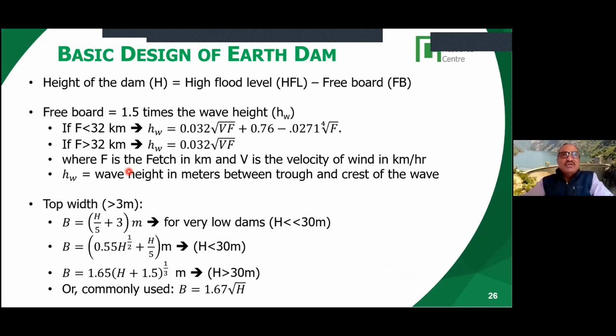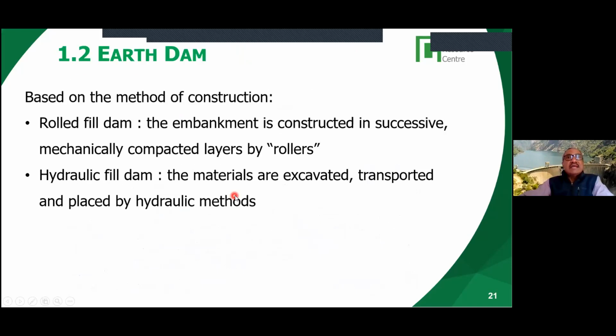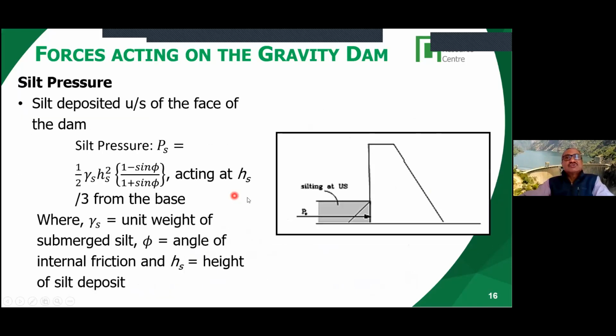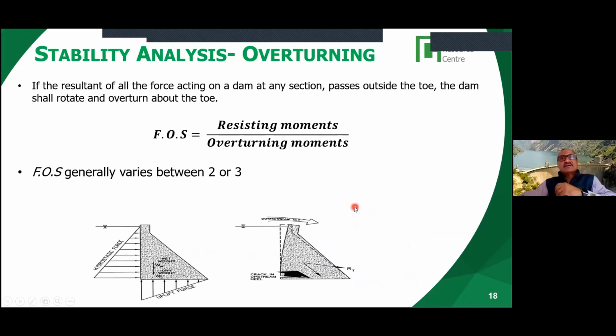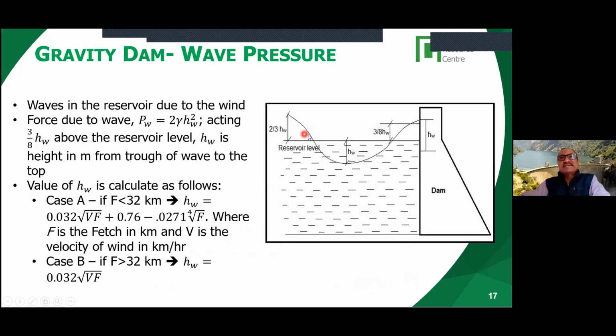So we use two methods. One is when the fetch is less than 32 kilometers; this gives the height of the wave that is created. From this figure, you can see you have to calculate the wave height HW.